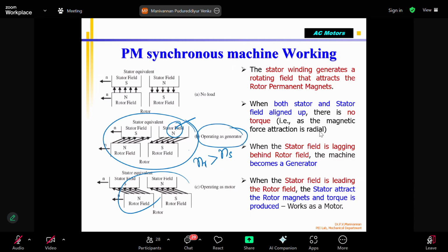In this case, rotor speed is faster, the rotor is driven by the wheel, correct? The wheel is driving, and to the stator, you are not applying voltage. The rotor magnetic flux is cut by the stator, and it generates AC voltage, that will be converted to DC voltage by a rectifier circuit, and your battery will be charged.